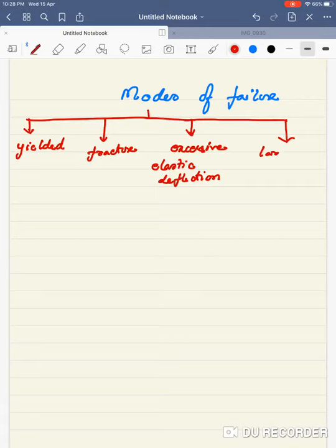and there's one more thing. So instabilities. For example, buckling, which we will not do too much in this course, but we'll try to touch upon at the end. Instabilities can also be regarded as a failure mode, because most of the time you do not want to have an instability, and the reason is that it starts extremely suddenly and it's very difficult to control after that.